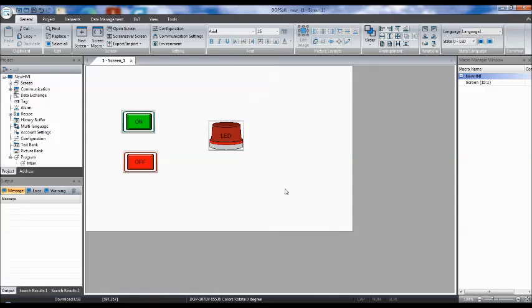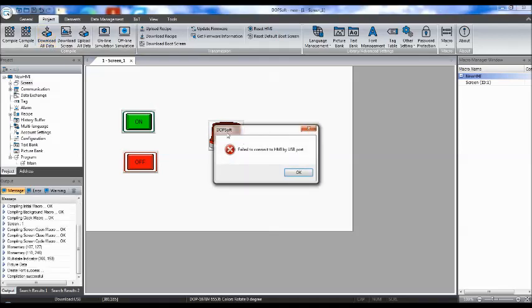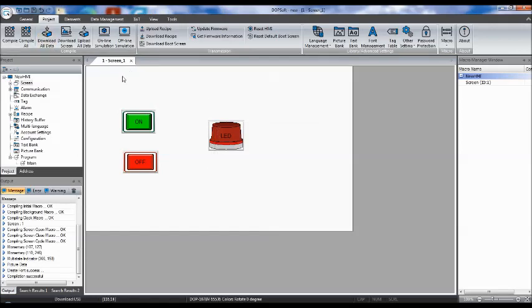So now, if you go to the simulation, if you have an HMI, then go to the project and the download all button. If you enter it, it will be downloaded to the HMI. You will see the output in my recorded video, that will be at the last. So just download this button. If the HMI is connected, then this screen will be downloaded to the HMI, and